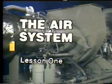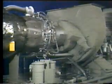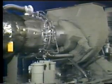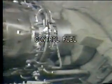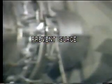Air System, Lesson 1. In the previous lessons, you have learned that air is used to create power as it passes through the engine. Air inside the engine is also used to control the fuel schedule, to cool engine hot sections, to form oil seals, and to prevent surge.